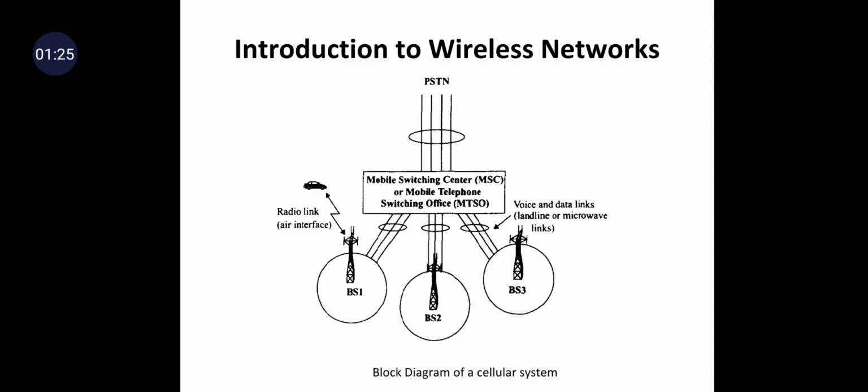All the base stations are connected to the MSC by voice and data links. It may be landline or microwave links. And there are many MSCs, that is mobile switching centers. They are all connected to the PSTN, that is the public switched telephone network, by fixed wired networks.